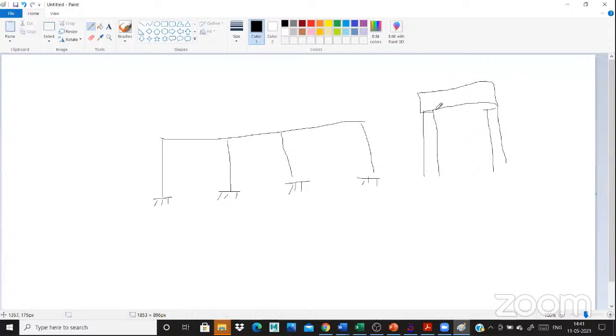I understand. In simply supported beams, the moments do not travel to columns. So your column will be minimum size and the beam will be higher size. Why? That is a condition. Understand? Your moment does not travel to the column in a simply supported beam. But in continuous fixed end support, the moment transfers to columns. That is a condition. These are the 2 conditions.